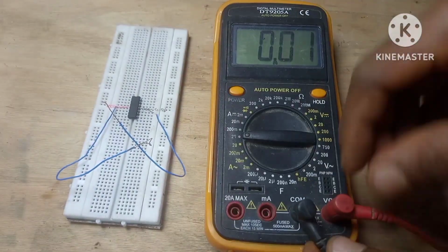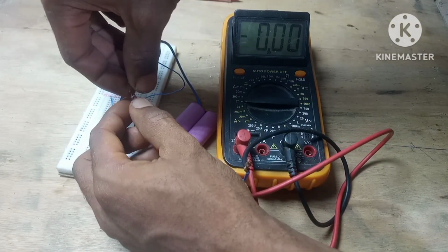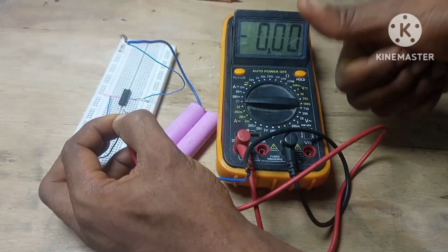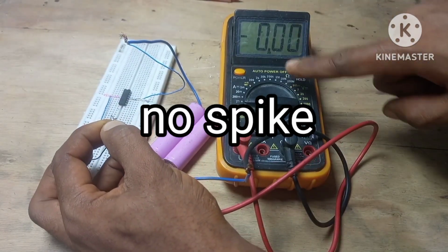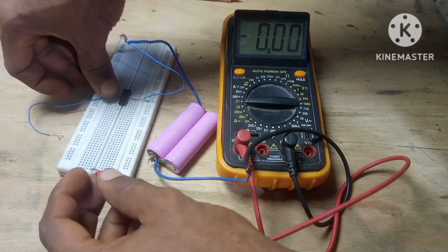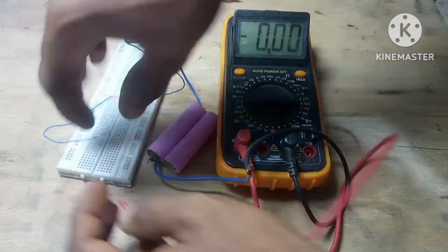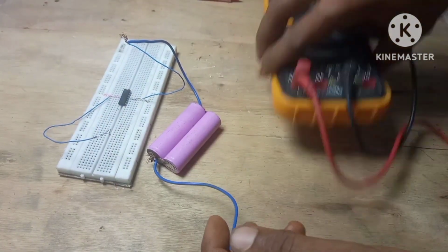Connect the IC, the power source, and your multimeter in series. Remember to set your multimeter to DC amps mode, and then connect the two ends together, like this. If the current suddenly spikes, stop immediately and use a much lower voltage. If it does the same thing with a lower voltage, then that could be a sign of a bad IC or a wrong connection.